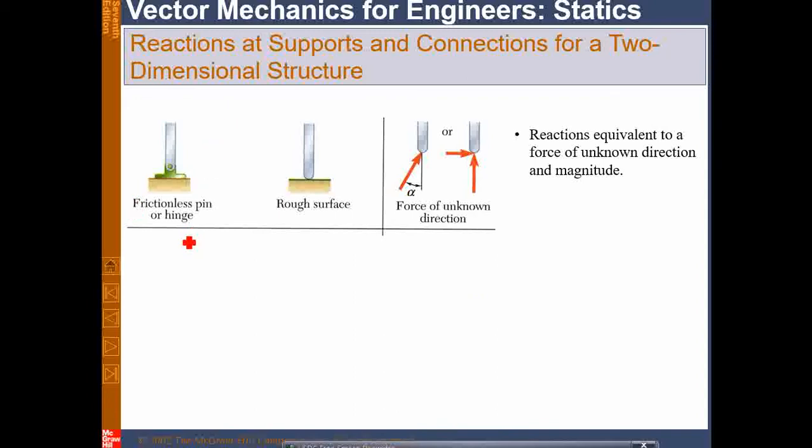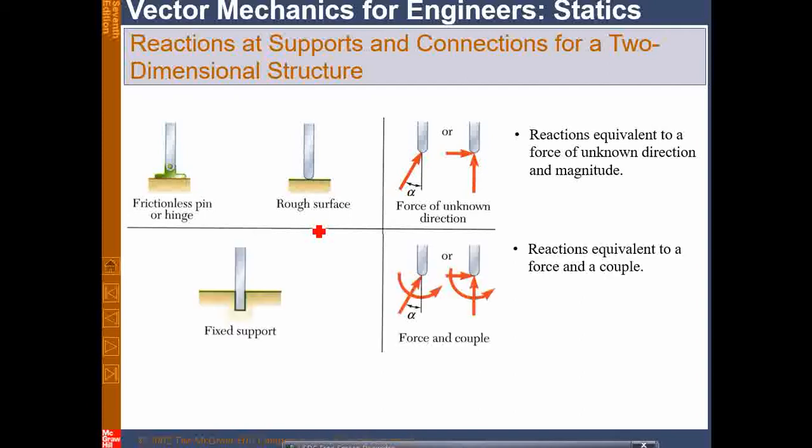These are only some of the examples from the usual applications. However, as you can see in the problem, you can see its movement along that particular range, and you put a reaction force if the movement in that range is restricted. If the movement in the other axis is also restricted, put the reaction force in that also. If the movement in the third axis is also restricted, then you have to put the reaction in that axis also. It's very simple.